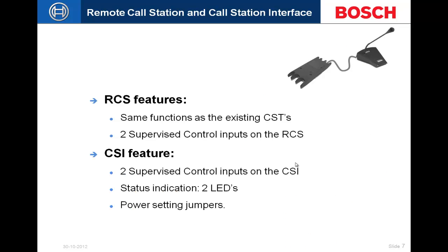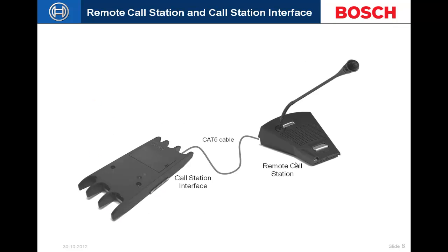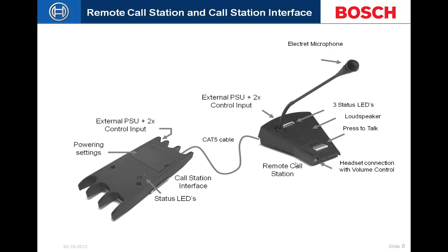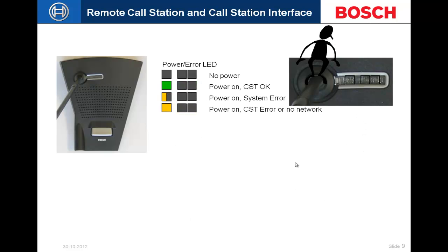Same functions as the original call station, same LEDs, same contact closures, same lights on the front LEDs. Essentially, it is identical, other than the network connection to the system. It is generating an internal ISDN line within that Cat5 line, so it is not analog audio. It is still digital audio over ISDN, giving you the ability to run through multiple locations without getting any kind of interference from lighting fixtures or any kind of high voltage interference.